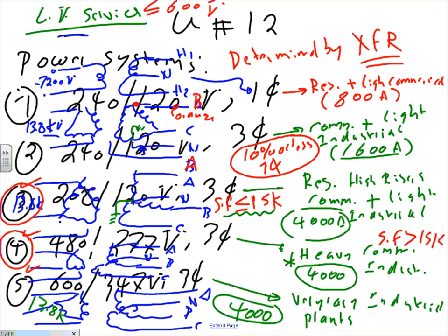Higher voltage, guys, always think of it as a smaller conductor, and also less voltage drop. Just to give you an idea, like 277, I can put close to, what did we say, 18 lights when we did our math. We can put 18 lights like this on a 20 amp circuit that's burning at 120. If you burn the same light with a different ballast at 277, you can almost put twice the amount of lights. Same wire, same overcurrent protection device. So you have a 20 amp. Instead of 18, twice of that will be 36, right?